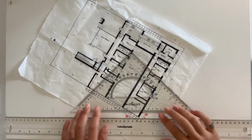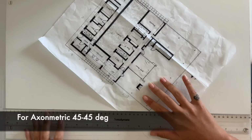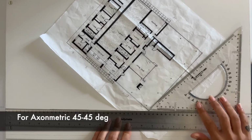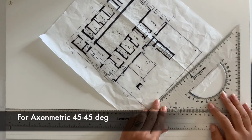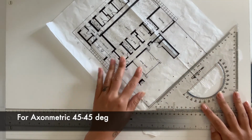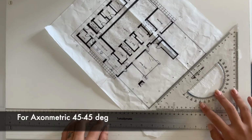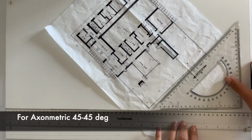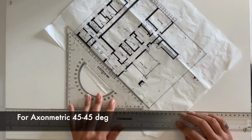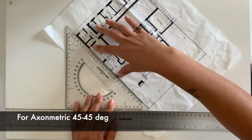There are many ways to achieve this angle. You can also use a protractor. To create a 45 by 45 axonometric drawing, you'll align your T-square up on your drawing board and place the corner of the floor plan to line up with the reference line, and then use your 45 by 45 ruler to slide across the T-square and just make slight adjustments until you can have that external wall aligned with the ruler. And you'll check the other side. And you just keep making slight adjustments until you get the correct angles.